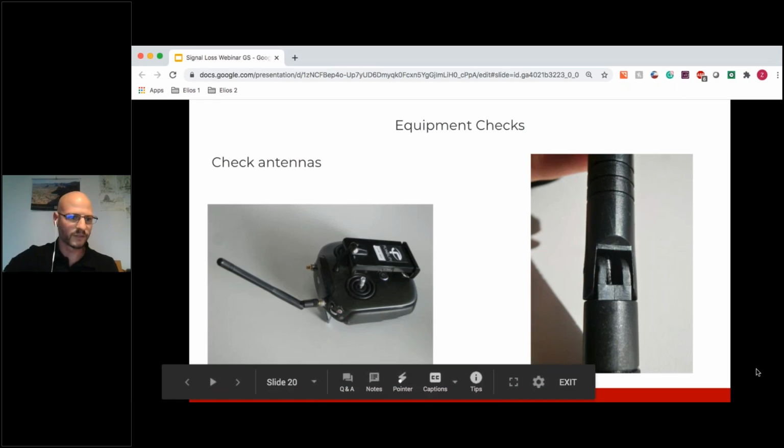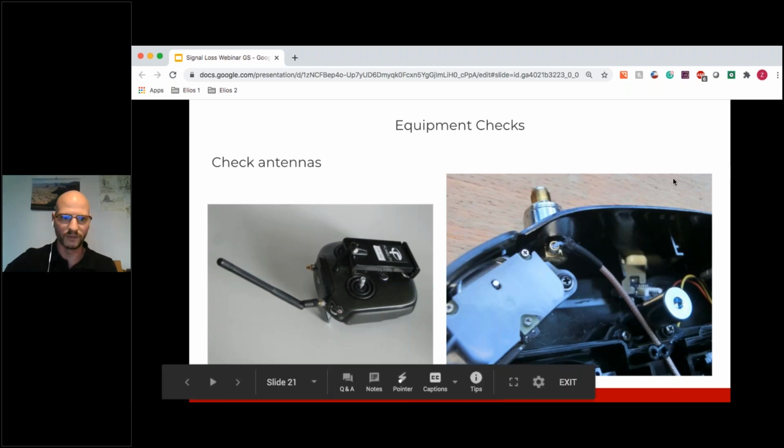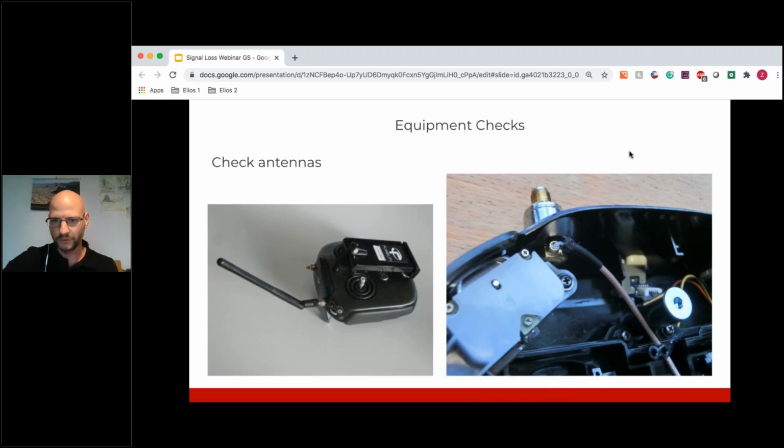The other thing, in the next slide, is that these range extender transmitters are modified to have an SMA connector, which allows you to unscrew the antennas and screw the range extender onto them. One issue if you screw the antennas or the range extender cables on too tight is you will start turning the entire SMA connector, and eventually, as in the right hand image, this will start untwisting the cable internally.